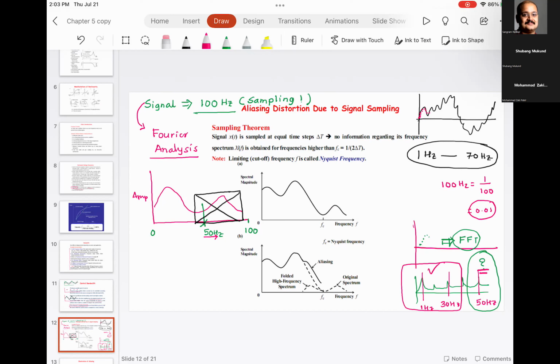Ideally, the most dominant frequency should be the programmed frequency, the frequency at which we want that shaker to vibrate. If the shaker is not vibrating at that programmed frequency, it means something is wrong. Then the most dominant frequency is the frequency associated with some other moving part. And then we see whether it's a blower, a cooling jacket, a pump, or some coil or some magnet, whatever it is.